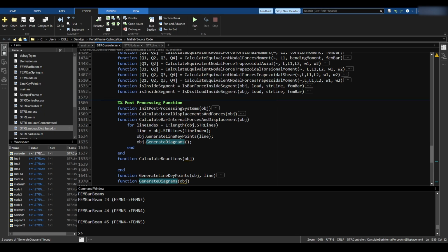Of course, if we allow in our software to have a parabolic load, then we would need to increase the level of the equation to become a power 4 equation. Because if we allow for a parabolic load, then you would have a cubic shear and a power 4 moment. However, we are not allowing for a parabolic load. We are allowing a maximum of a linear load, which means that we are safe in assuming a cubic equation as max. Today, we are going to build the basis of the diagrams and the cubic equation. It's going to be nice, not really that complicated. So let's enjoy the show while it lasts.